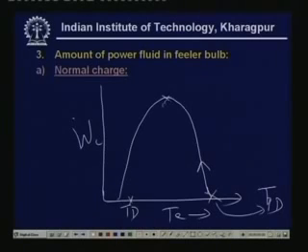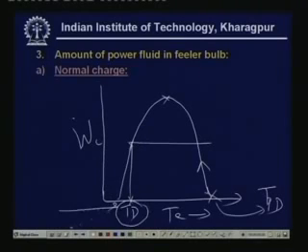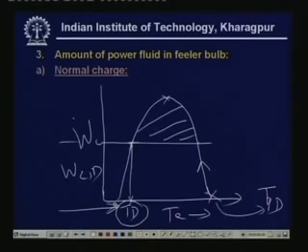And it reaches a peak, then it comes down, and finally comes to the design point, right? That means if you have selected a motor which will operate satisfactorily at the design point, that means if your motor gives only this much power, design power, then during this portion the motor is overloaded, right? So this is what is known as motor overloaded during the pull down time.